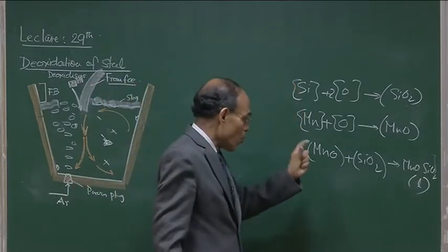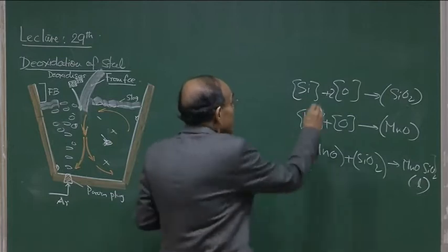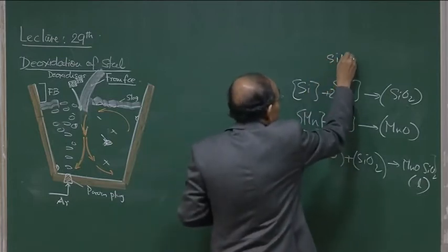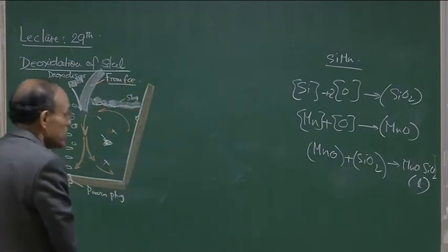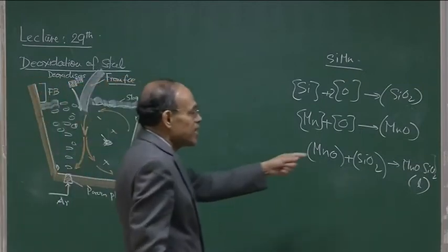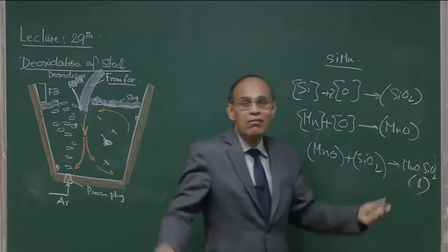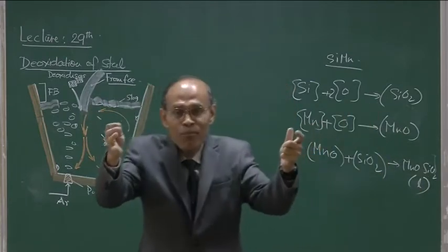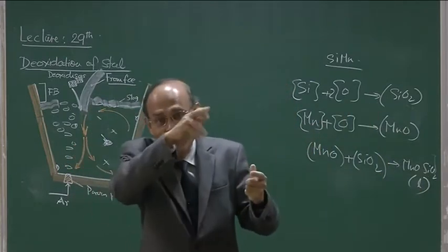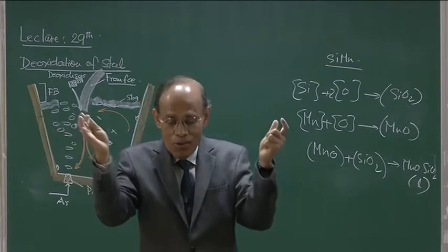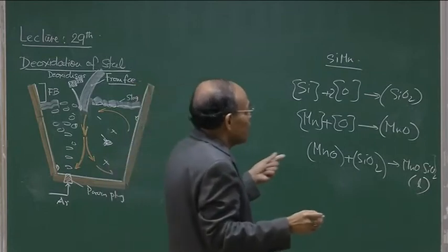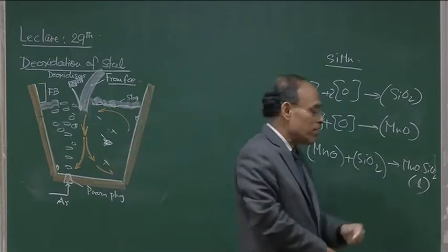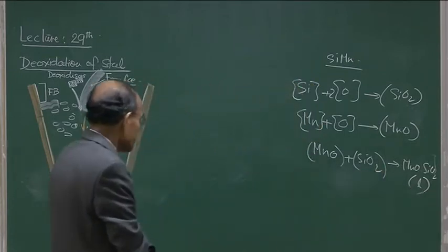So the composition of silicomanganese is adjusted in such a way, nearly 1:1 proportion, such that you can look at the manganese silicate phase diagram, for example the MnO-SiO2 phase diagram, and find out where liquid phases originate. So you may have a range of compositions where you can have deoxidation and yet have liquid products.